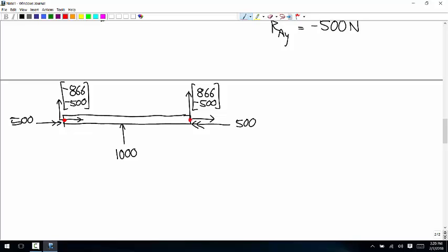And now those 2 points are already taken. So anything else that happens at those 2 points, we don't have to count that again. We're only looking for points where we have to deal with these subfunctions changing. So now we're looking for points between those two where we have point forces, point couples, or distributed loads changing. And the only place where that happens is here. There's a point force in the middle.